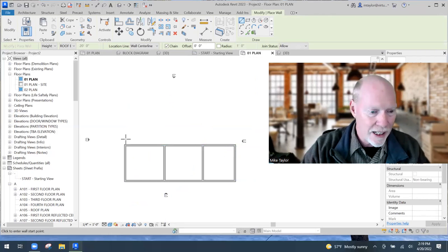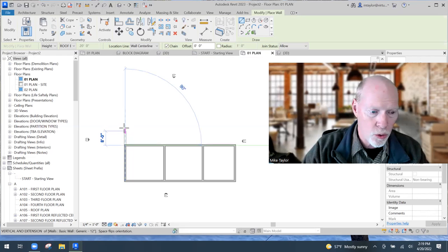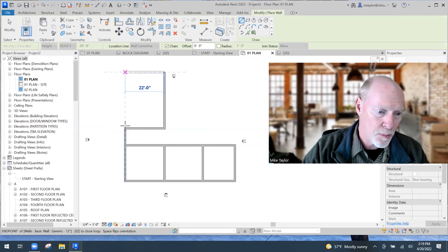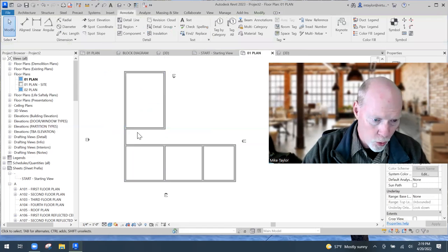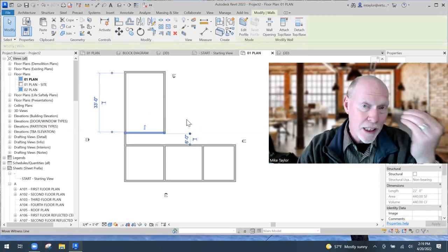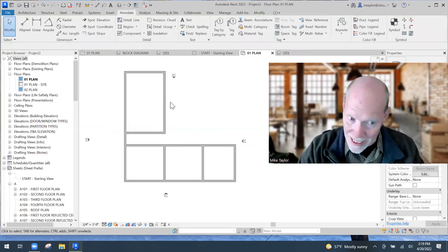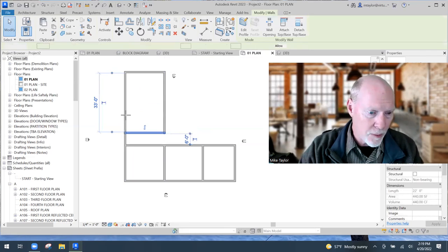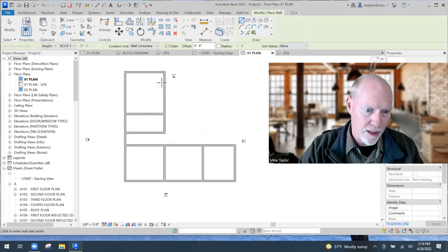And yes, I do need a corridor, and then I'm going to need maybe some more spaces over here. Let me see. The corridor only needs to be 6 feet wide, so I click on it, say 6 feet. So you be a little more realistic while you're sketching, okay? And then say, I need a wall right about here. So if I could put a stair right there, and that could be an office there maybe.